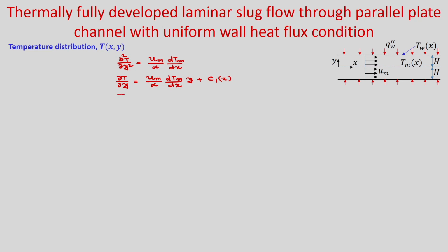And another time if you integrate, then you can write T, which is a function of x and y: T = (u_m/2α)(dT_m/dx) y² + C1 y + C2, C2 a function of x.